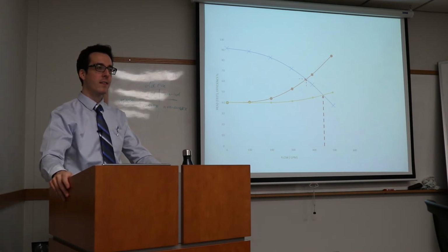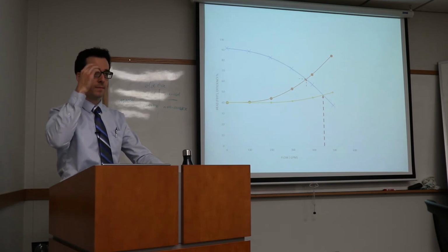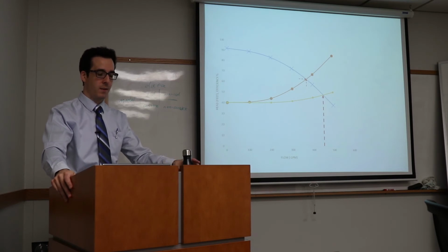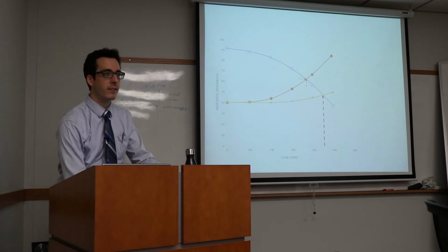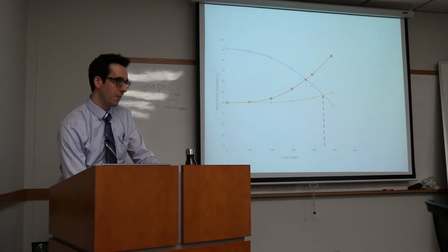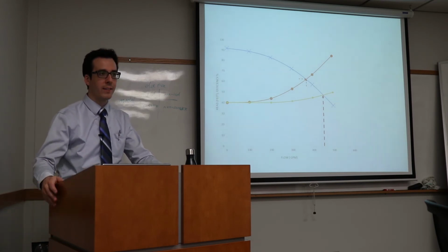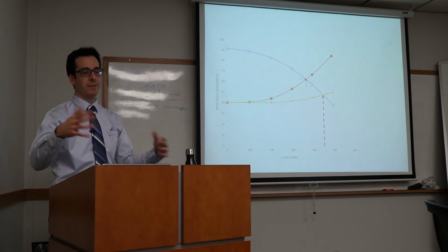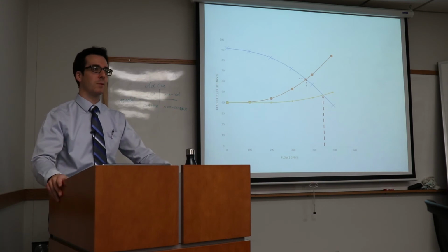Yeah, James. Out of curiosity, how is head measured? If there's a simple answer, great. If not, so. Yeah, so when we do this in our firm, we use a hydraulic simulation to figure the head. Sometimes we make field measurements, but it's pretty well known at that point, and we calibrate that in the model. And so we do a few runs at different flow rates and plot these points, and that's what we design to.